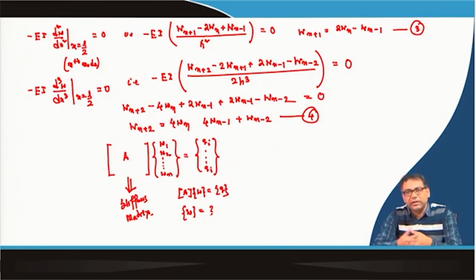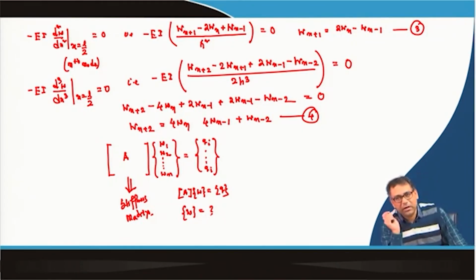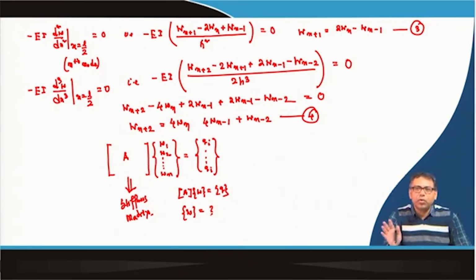Then you solve this equation, or you can use MATLAB, or you can develop your own code, you can use any solver, and you will get the deflection at any point. Once you get the deflection at any point, then by using the finite difference method also, you will get the slope, bending moment or shear force at any point.